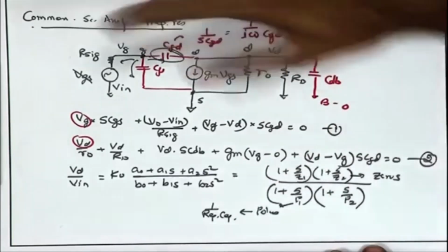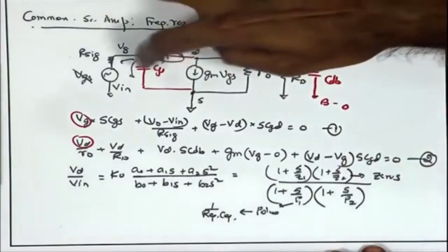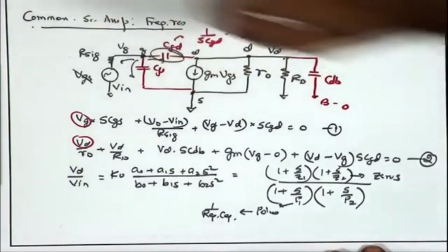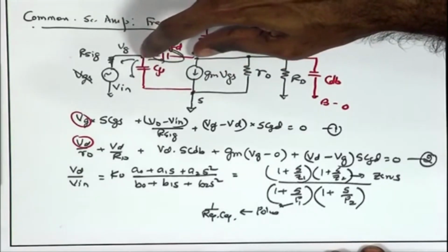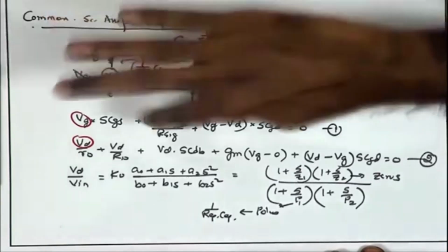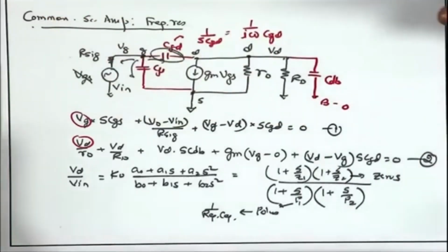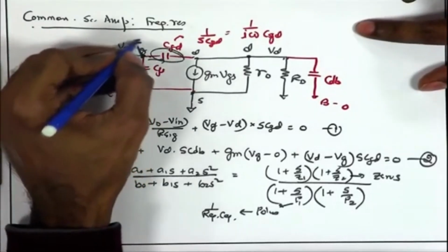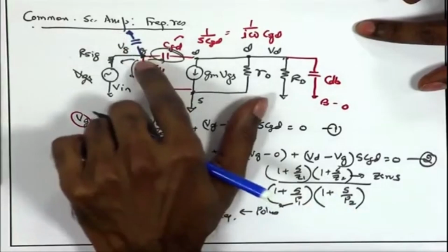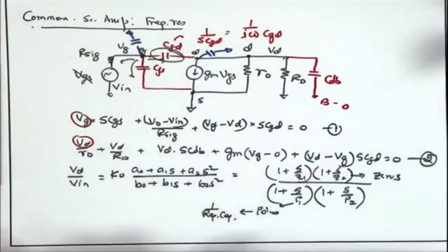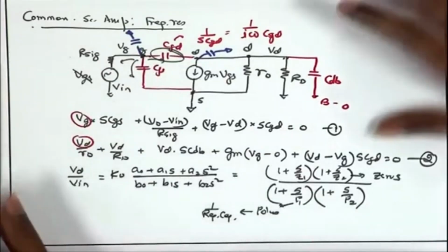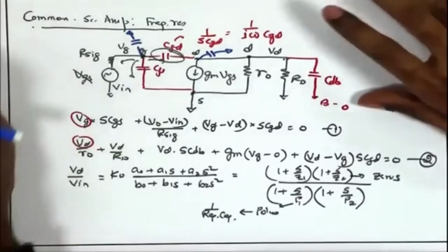So, that is the main motivation behind using Miller theorem to decouple or disconnect the small signal parasitic capacitances connecting two circuit nodes and represent them by equivalent capacitances connected between those particular nodes and AC ground. So, what I would like to do is get rid of this CGD and represent this as an equivalent capacitance between this node and AC ground, and likewise between the other node and AC ground. This is what we would like to do, and Miller effect comes handy. That is what we are going to use for doing this simplification. So, without going into the proof of Miller effect, which can be done in 2 lines, I am just avoiding that.